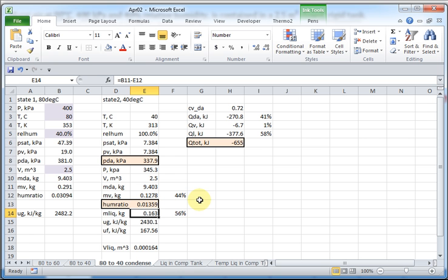And then that's 56% of the initial vapor. So quite a bit of the water has condensed. And you have to look up u_f for that temperature of 40 degrees C, u_g for that temperature. And when you calculate the total amount of cooling required, it's a lot higher, 655 kilojoules.